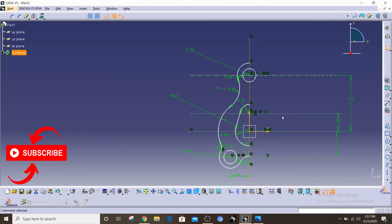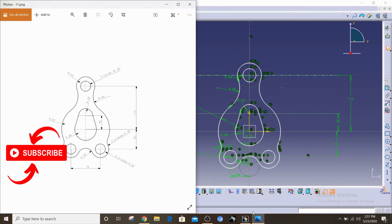and then we're going to use the mirror property to basically copy and paste the one half of the whole sketch to the other side. So I'm going to select all of it, and I'm going to use the mirror property selected, and I'm going to use the axis that we have to mirror it against. So I'm going to use the central axis, and voila, we have a perfectly symmetrical sketch on the other side as well.